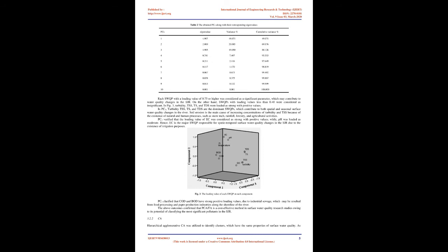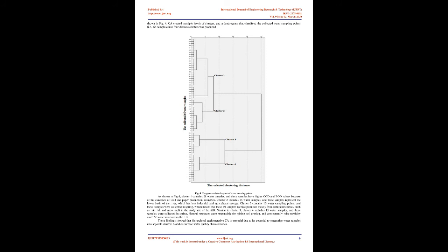TS ranged from 58.00 to 245.00 mg/L, and TDS varied from 52.40 to 233.85 mg/L. While COD ranged from 4.80 to 86.64 mg/L with an average of 27.55 mg/L, BOD levels were 1.21 to 3.25 mg/L with an average of 1.75 mg/L.